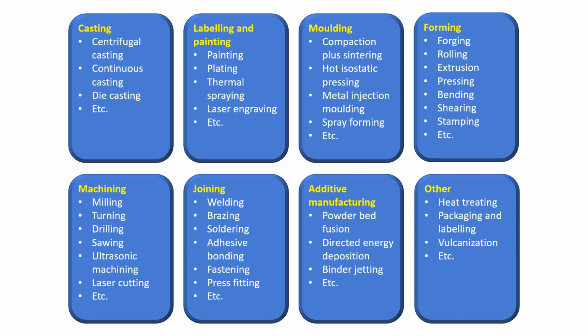Parts that are well suited for AM methods have in common that they are able to take advantage of such AM process advantages as complex internal and/or external geometry, custom geometries, low production volumes, etc. On the other hand, as AM methods and materials evolve and new solutions enter the market, the scope will also expand. By the way, did you know that we currently have about 20 different commercial AM processes for metal 3D printing available, and the number is constantly growing?